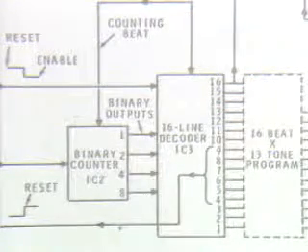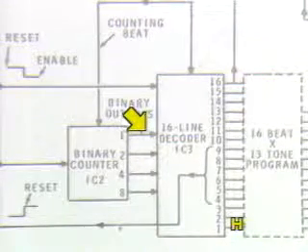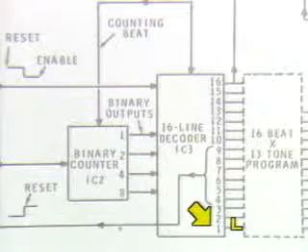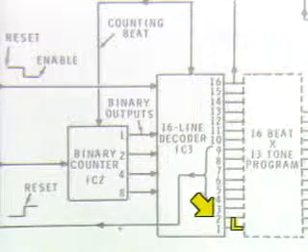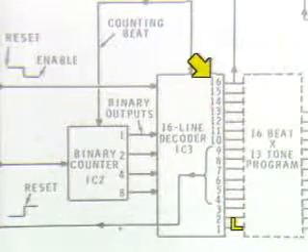The binary numbers produced by the counter are decoded by integrated circuit IC3, which is a 4-input, 16-output decoder. As a binary number is input, the decoder sets the corresponding output to a low, while all other outputs remain high. This occurs for each of the 16 outputs in succession.